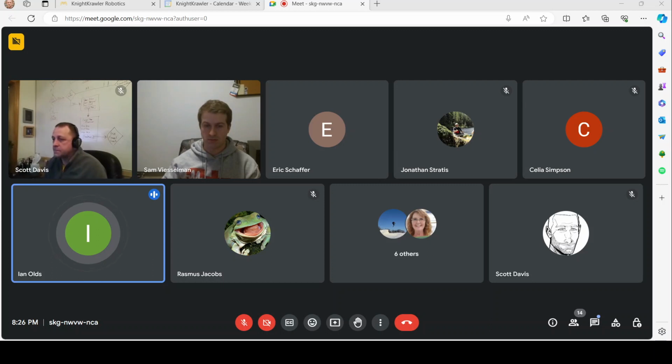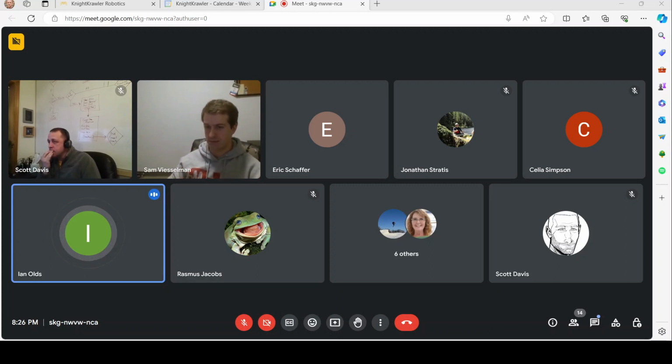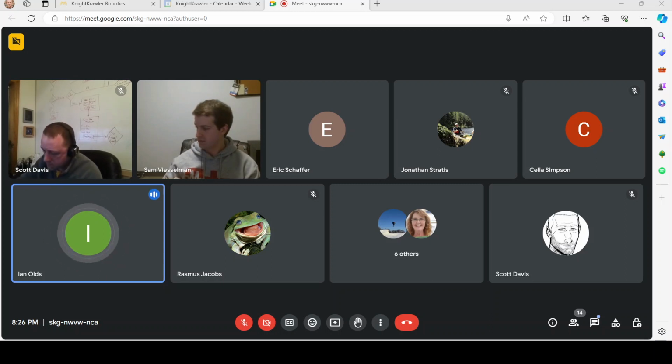Another thing that we're doing is we throw away all rotational resets from April tags because we don't want our robot to have our gyro reset by the April tag. We trust our gyro way more. We also have a bit of code on the side, because the targets that you get from PhotonVision have a lot of information, like this is the ID, this is the rotation, and all this other stuff, so that we can actually crunch the numbers. When we were testing this out early in the build season, they spent like 2 weeks just playing with it.